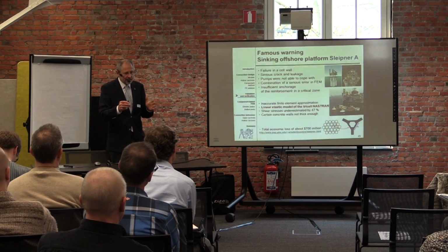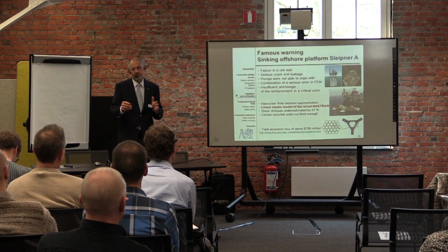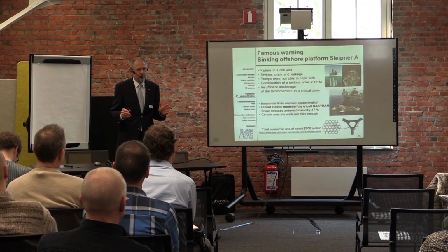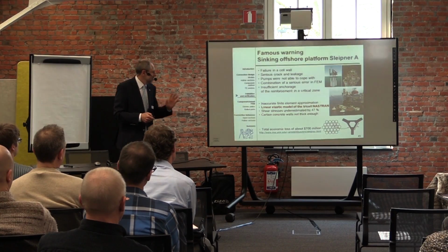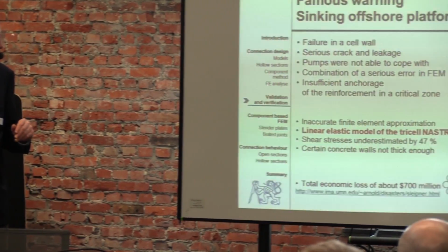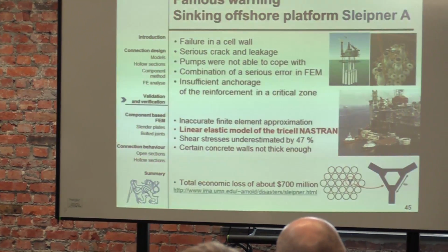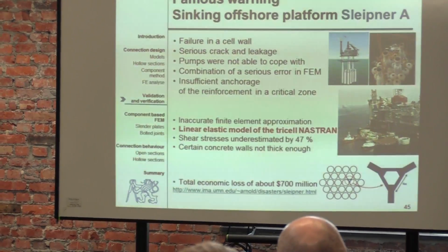The cells they calculated by linear calculation, and also they slightly under-designed the walls, and finally cracks occurred, they sank it, and they lost the platform. Unfortunately, they had already instrumented it, so it is the most famous disaster due to not proper use of validation and verification.